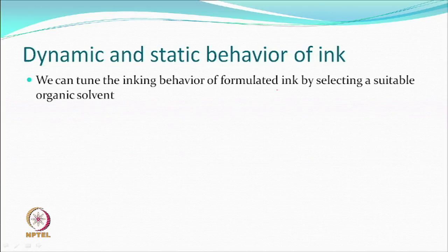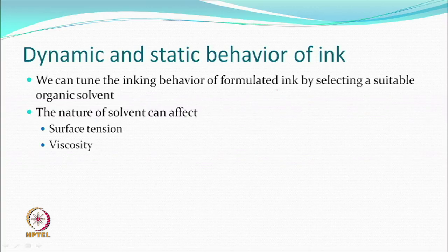But when you are not printing, let us say one of the colors is not being used in that design so much, or the machine had been stationary, there is a drying of the ink at the edges of the nozzle. That can become a particle, a solid material, and so it can cause some issues. So, organic solvents are used. When you add organic solvents or anything else, the evaporation rate can be changed. The nature of the solvent can affect the surface tension and viscosity.